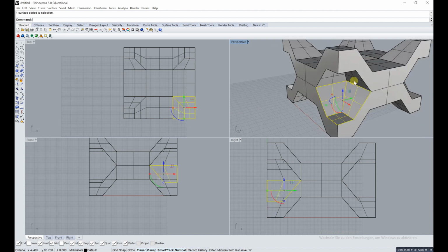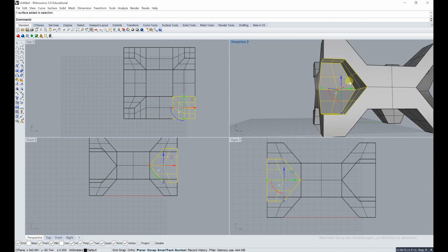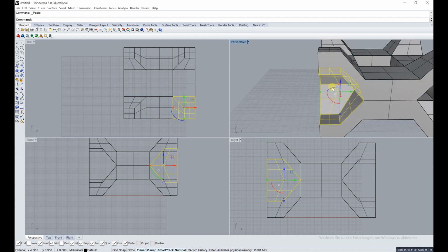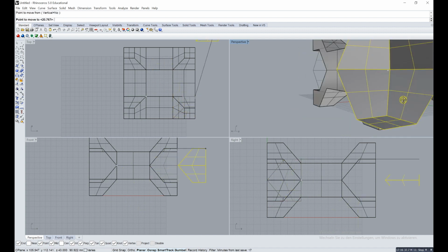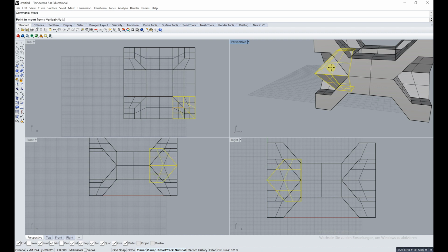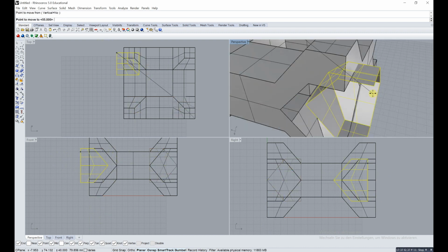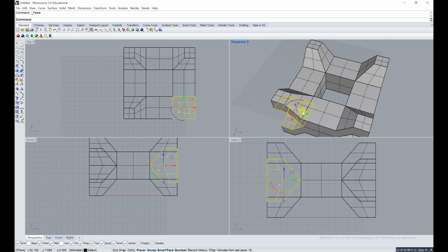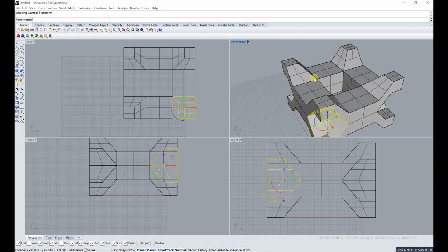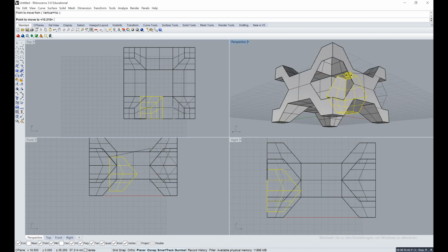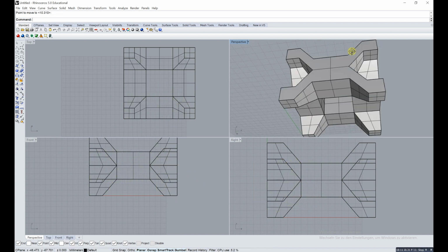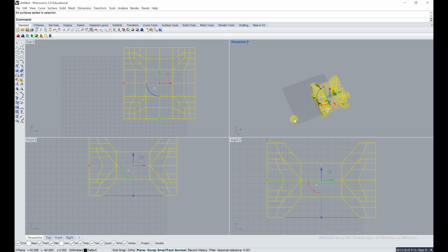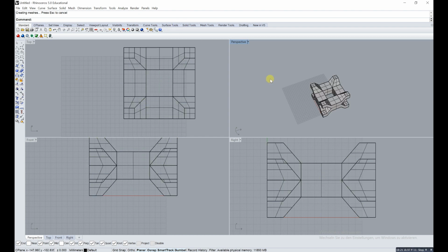And then take all of them, copy them, insert them and rotate them and just move them into place. Just do that for all 4. So they're all together now. Just select everything, just join it together. It needs a moment because it's creating the mesh, and now one poly surface is done.